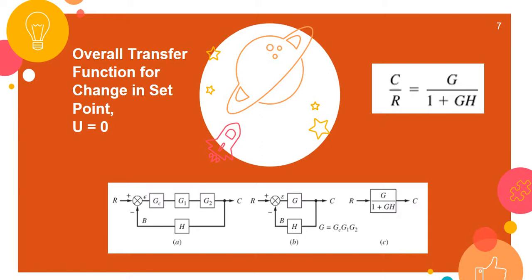You know how to do that. You just simply multiply the three, and that would be your G here, and you have your H here, and you have your set point here. Anyway, the G is already specified in here. When you have written your block diagram in this particular form, from this, it would be easy to write the transfer function of your system now. This is your output variable, this is your input variable, and these are your transfer functions.